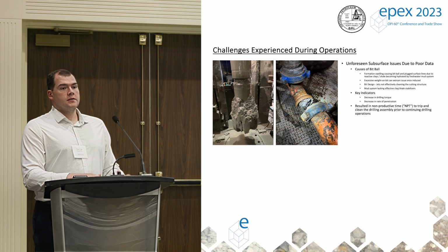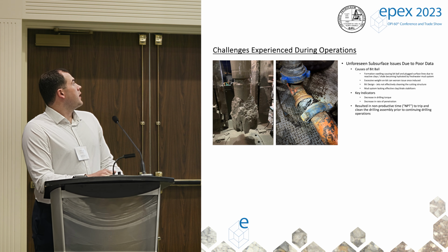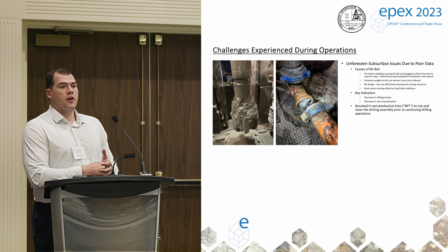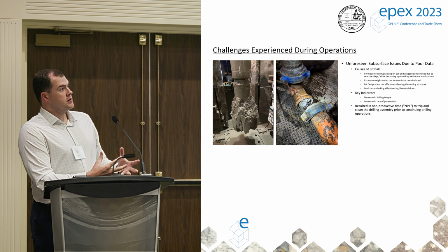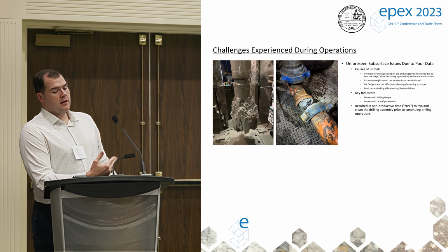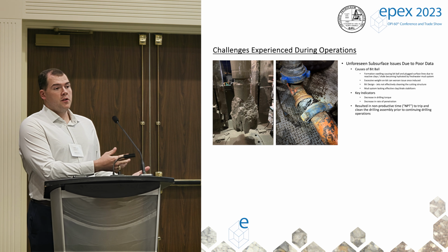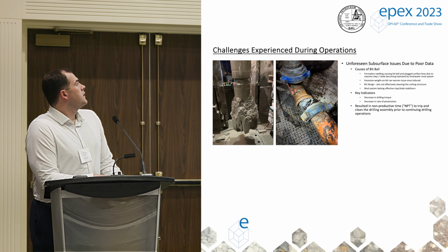So instead of 20,000 pounds, let me stack 30. Well, then let me stack 40 and 50. What happens is your cutting structure actually gets covered by the mud and it slicks up like cake, where you're not cutting, you're not grabbing rock and biting anymore. And as those issues continue to happen and you're not adding clay stabilizers and inhibitors into your system, you start having those issues with mud rings and stuff returning to surface, packing off your flow lines, etc.